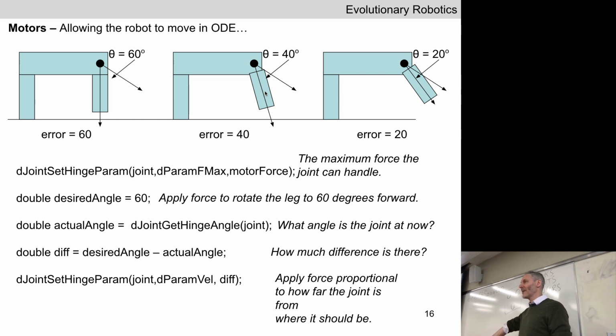Remember, physics engines update position and orientation. So now the object is here, and the current angle of this joint is 20. It was 0, and now it's 20. I still want this joint to rotate this object to 60 degrees, extend this object out 60 degrees away from this object. So far, so good?